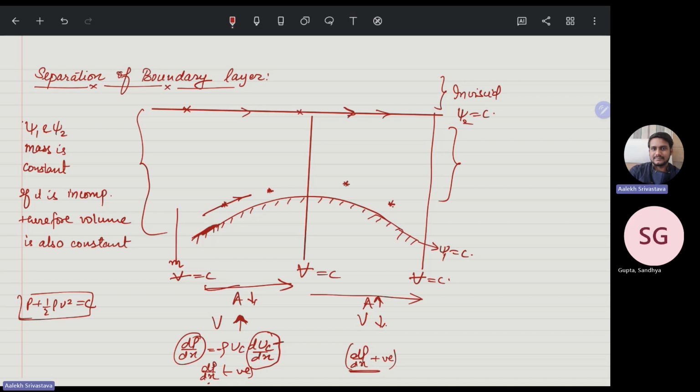Now here it says that here you have a lower pressure gradient, here you have a higher pressure gradient. Now what is the meaning of this? If you don't have sufficient velocity in this direction, the inertia force, the flow will happen from the back side. And this is called separation of flow, because now the boundary layer will, like if I draw the velocity profile, the velocity will look like this. But at this point, the velocity will look like this. Now the flow has separated and it has reversal. So that is called the flow separation. The flow has been separated, like so.